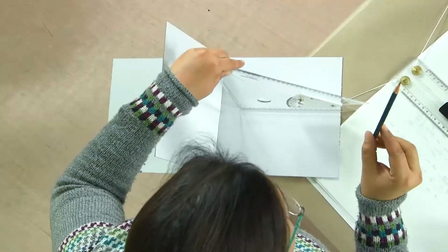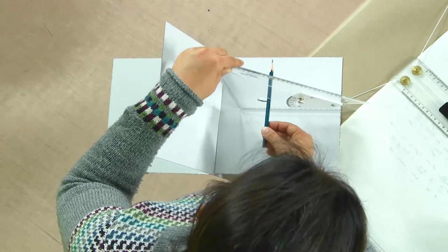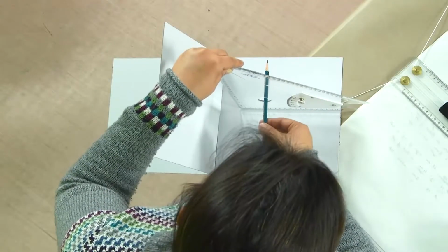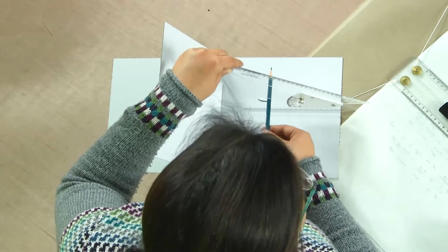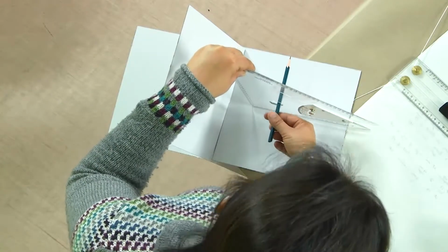Another thing, when we have to classify these different types of planes, is to also see where the axis of the plane lies. A line which is perpendicular to the plane is called its axis. In this case, when the plane is perpendicular to both the reference planes, the axis is parallel to both the planes. When the plane is parallel to a reference plane, the axis of this plane is perpendicular to that reference plane.